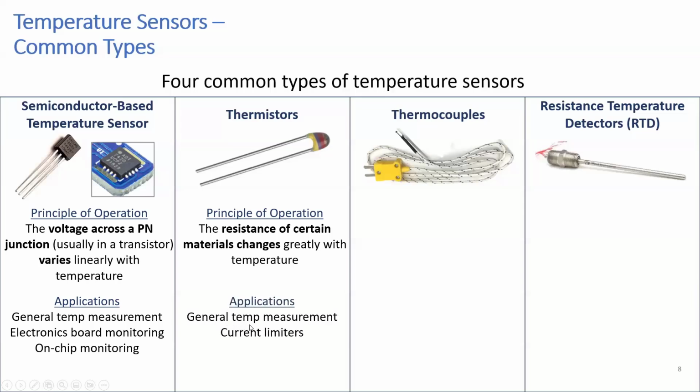And these are again used in general temperature measurement. But another application I'll show you is for current limiting. They act like a natural current limiting device. I'll show you that. If you have a device where you don't want too much current going in, because something's wrong if too much current is going in, you can limit the current with these.